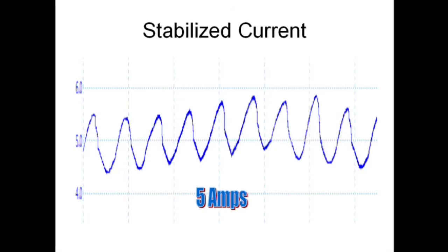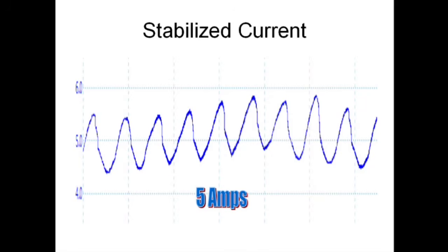Now, as you can see, the pattern observation of the fuel pump is the rotational motion of the armature and the brush contact on the fuel pump armature. We're not really holding exactly at 5 amps. We're kind of dancing above and below 5 amps, which gives us an average of around 5 amps. After that rush-in current, the current flow is going to drop down and stabilize.